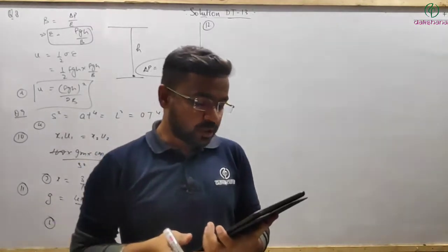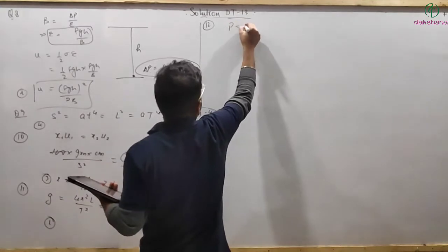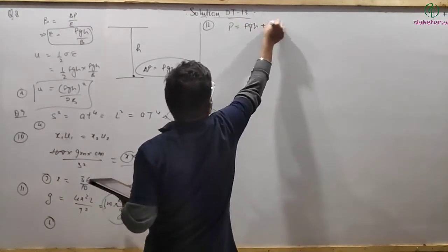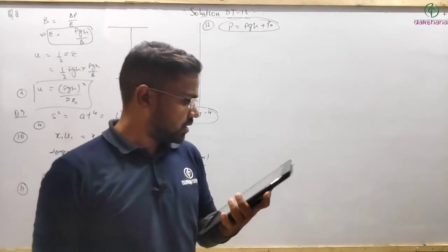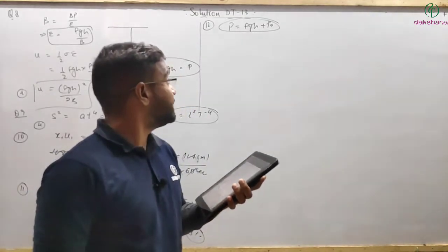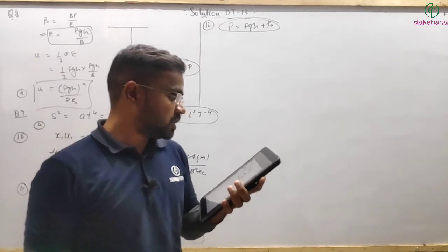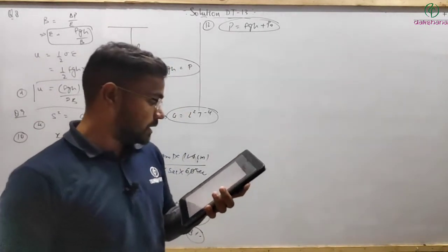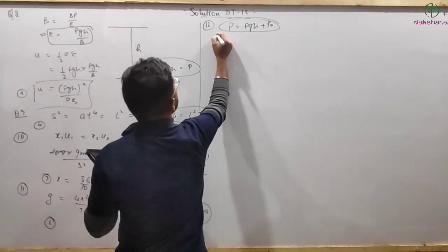The pressure at the bottom of the tank containing a liquid depends on rho g h plus p naught at the bottom of the liquid. It depends on acceleration due to gravity, and on the height of the liquid column. The area of the bottom surface does not matter, but the nature of the liquid, meaning its density, does. So the right answer is 3, does not depend.